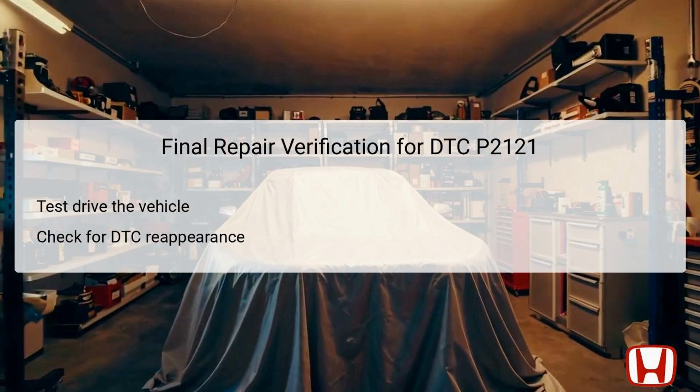After completing all the required repairs for DTC P2121, it is vital to conduct a thorough test drive of the Honda Fit to verify that the repairs were effective and that the vehicle operates correctly. Monitoring behaviors, particularly in throttle response, acceleration smoothness, and check engine light status, provides critical information on the success of the troubleshooting process. After the test drive, reconnect the HDS to scan for any returning DTCs.